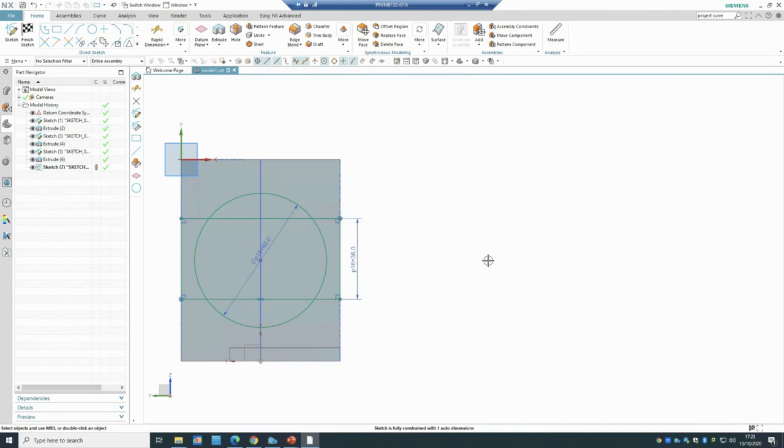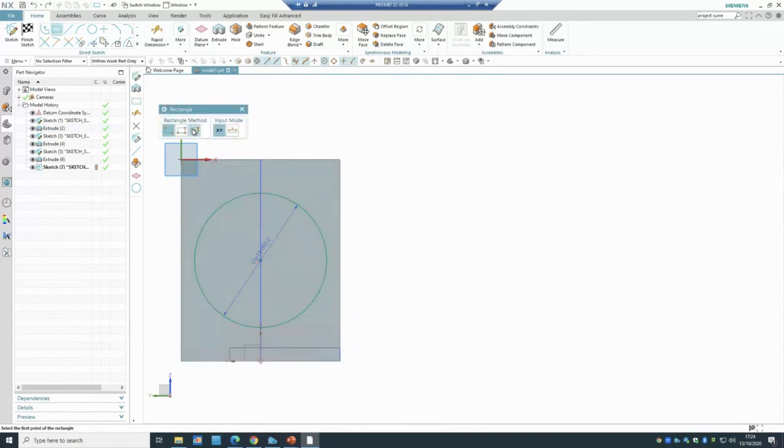And everything's fine. So what I will be able to do, in creating a rectangle, you can do it two ways. You can either come back and manually make every single one of these equal to each other, or you can go to the rectangle and use this one, which always starts from the center. Let's see what's the difference. So if I do from the center, then it automatically lets me put the 0. So it automatically gives me the option to just put this one as 36.